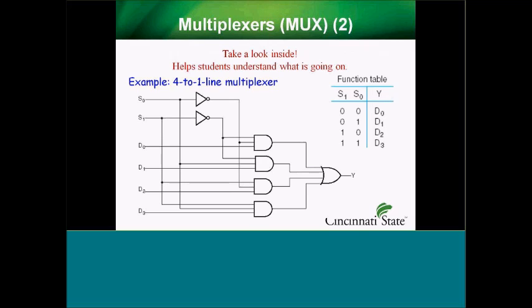This is as I was telling them what is actually going on inside the multiplexer. Basically looking at S0 and S1 being the signals, the control lines, and then basically they can see. And this is another thing that I constantly have to get at them about, and that's the concept of just looking at the AND gate, and whenever you have a 0 on the AND gate, it's 0 on the output. It turns out that's such a fundamental concept in digital logic. I cannot overemphasize that enough.